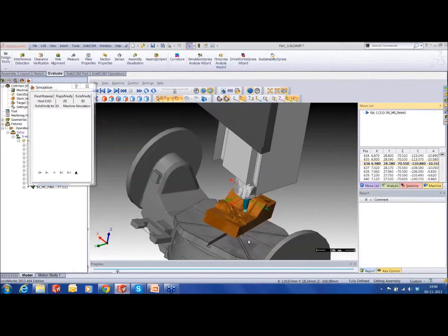One of the most critical applications in die mold for 5-axis is to machine these areas where the radius is pretty small. You can't take a small diameter tool to that length because 110% it's going to break, or it will leave a lot of vibrations and chatter on the surface. So one of the most critical applications is to machine such small areas without having to have a lengthier tool of a small diameter, so that you don't get any vibrations. The finish is excellent because you're using the shortest possible length to machine that particular area. All right, let's move ahead.